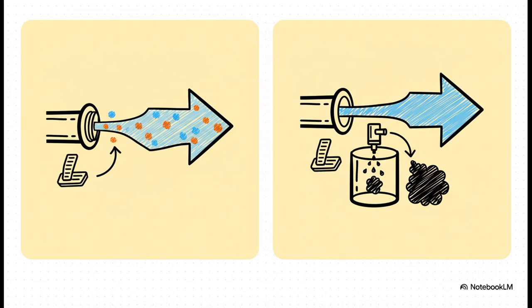This lets more of that pre-made air and fuel mixture into the engine. More mixture means a bigger bang, which means more power. Simple enough. But a diesel engine doesn't even have a throttle. It's always gulping in the maximum amount of air it possibly can. To go faster, you just inject more fuel into that hot compressed air. It's a much more direct way to control the power.